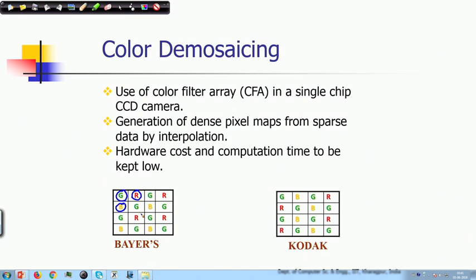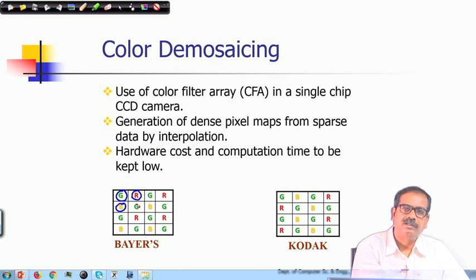We will be discussing different methodologies for that. In the given problem, what is fixed, what is already provided, is the interleaved pattern of channels that is standardized with respect to the pixel coordinates. So, at every pixel of the CFA I know which spectral component is available at that array location. You should note that these positions could be encoded by two different indexing schemes.